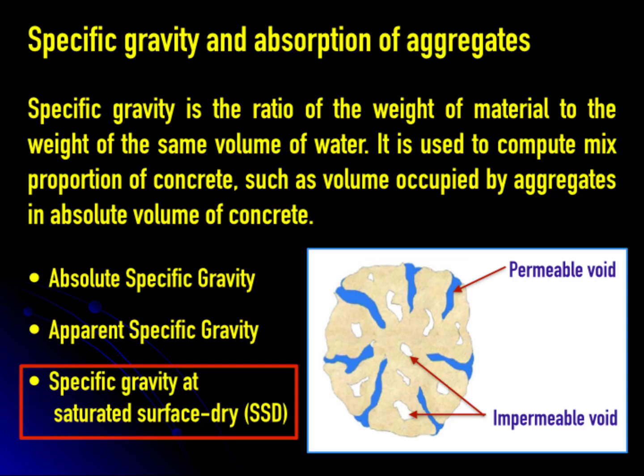So, if you prepare both aggregates at the same weight for mixing concrete, the water or moisture content in the aggregate is very different. The concrete made from wet aggregate has very high slump or may be too wet, while concrete made from dry aggregate has very low slump or zero slump. Although both concrete mixtures have the same aggregate portion, they are much different in workability and do not control the concrete quality.